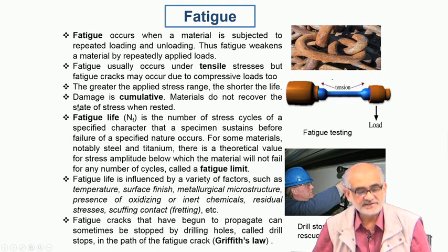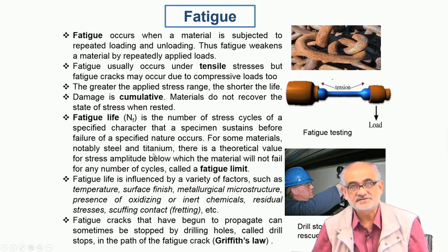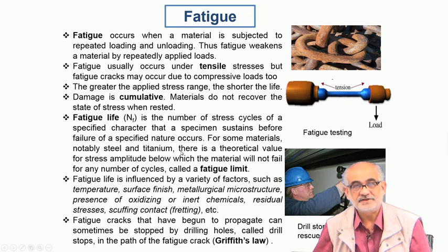So anyway, for the designers, what is important is to determine this fatigue life, and fortunately for metals, you actually can define what is known as endurance limit, which essentially defines the stress amplitude, or the minimum stress amplitude, which a material can withstand no matter how many cycles of loadings are applied. In other words, if you are applying load below the endurance limit, then in metallic systems one can go even up to infinite number of cycles and still the material is not supposed to fail due to fatigue.